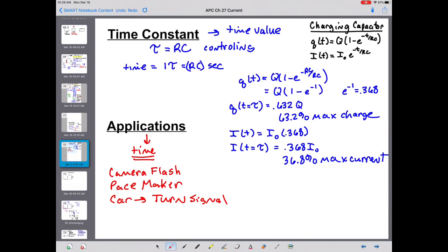What's happening there is, in the RC circuit, the resistance value has changed because now you have a burnt out bulb instead of a good bulb. With a different resistance value, that changes the time constant, and with a different time constant, you reach the discharge voltage more rapidly, and so you discharge more rapidly and you get a rapid flash.